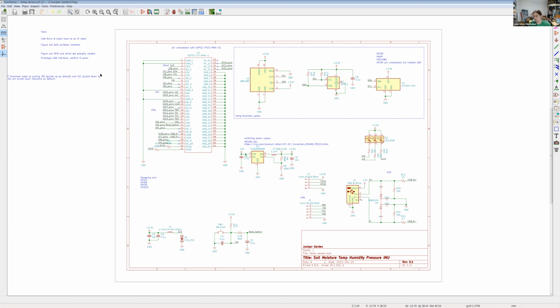I actually have on the board three different temperature sensors or footpads for them: the BME280, the SHTC3, and the Si7020. On top of that, those pads are also used by other vendors, so they're pin and chip compatible with I think a couple other vendors' worth of temperature humidity sensors.